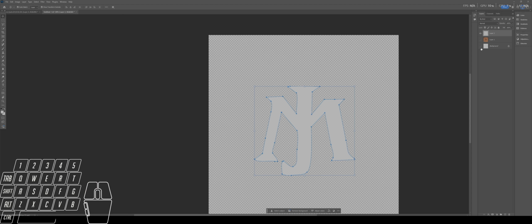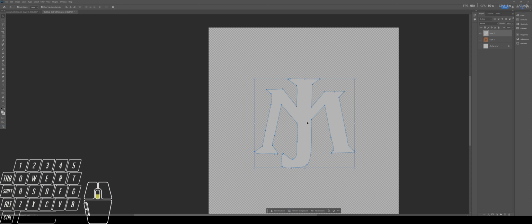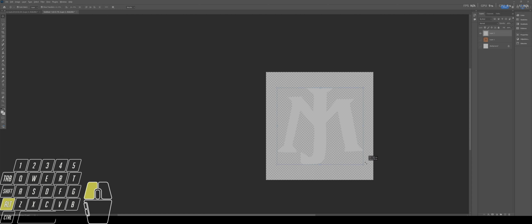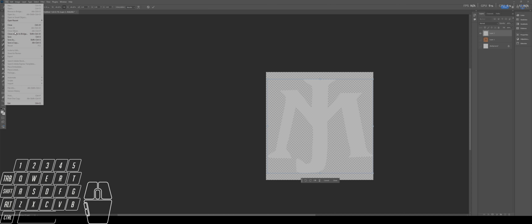Now if I hide that background, I've still got that path, but I've just got this M intersecting with a J as a color image. It's really important that we have this color of white because it works as part of an alpha channel, what we call an alpha map within Maya. I'm going to export this with transparency in a minute, and anything that's transparent is just not going to be registered with the software, but anything that's white is going to be interacted with as signal that the stencil in Maya can utilize.